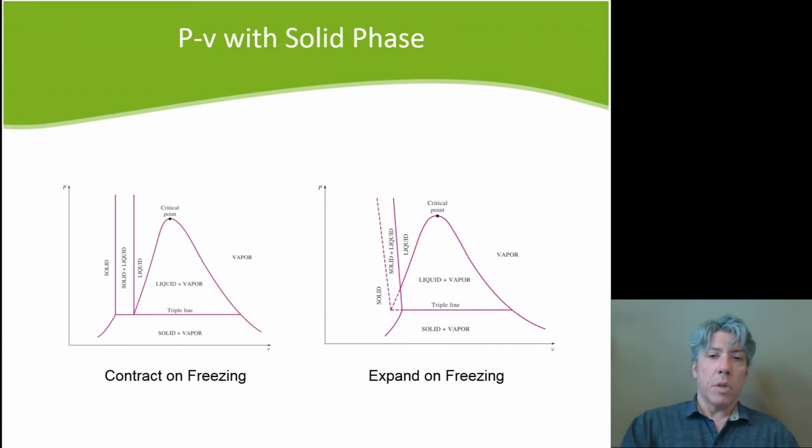actually changes. So these can be a little bit difficult to understand, but you can see on both of these that there is a region where the pressure is low enough such that solid and vapor can be in equilibrium with one another, and this is called sublimation. You may have seen it with dry ice, for example. You may have done an experiment in chemistry class where you had a vessel that you put ice in and you reduced the pressure so much. We did it in chemistry class with running water in a Venturi. Well, where you've reduced the pressure so much that the solid sublimates. It changes into vapor, and if it's in equilibrium, the vapor can change back into solid directly without going through the liquid phase.